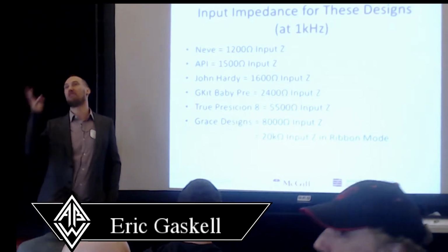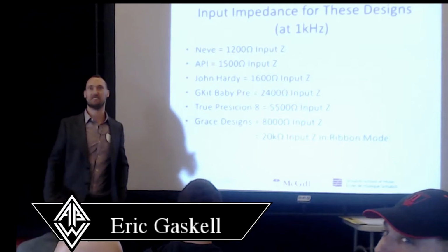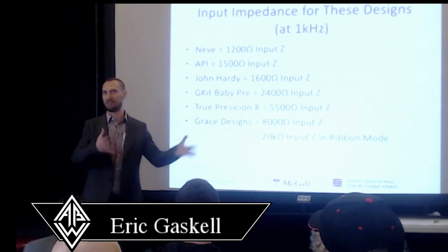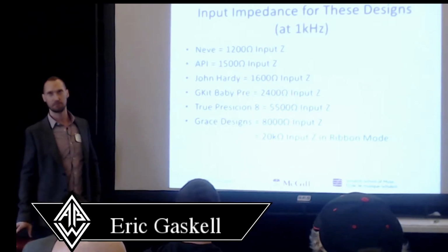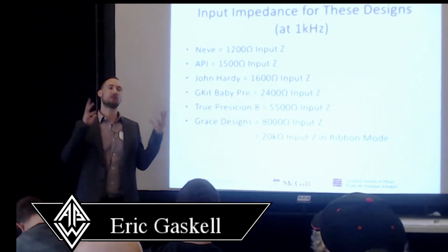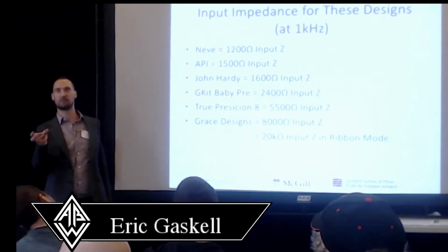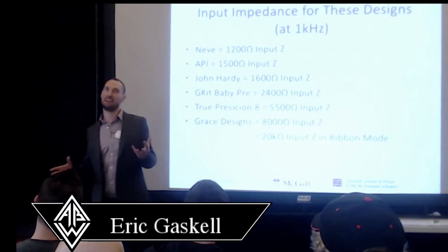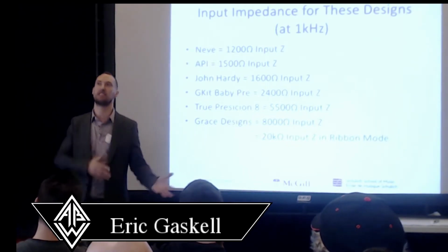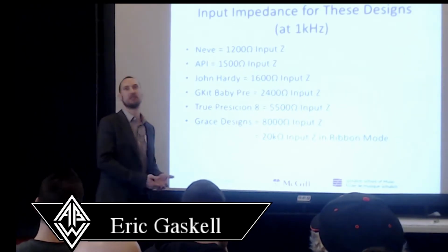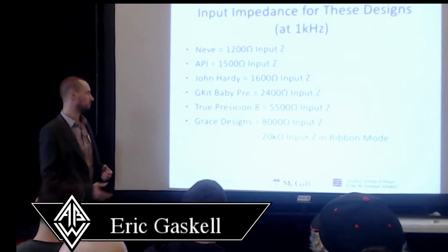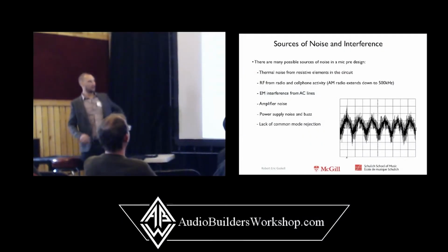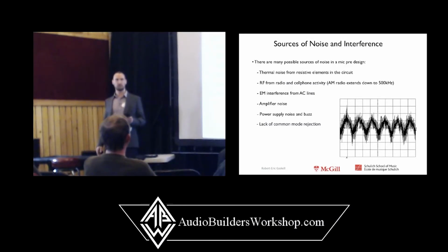But 300, I honestly don't know of any designs. I think it's just there to mess with things, you know. And if you want to really hear a difference, then yeah. I imagine it would make your mic darker depending on its output characteristics. And it only affects dynamics, like you said. If you have a condenser microphone that has a transformer buffered output, there's potential for some interaction there, but again, it's going to be much less significant than with a ribbon microphone or a moving coil dynamic that has no actives.